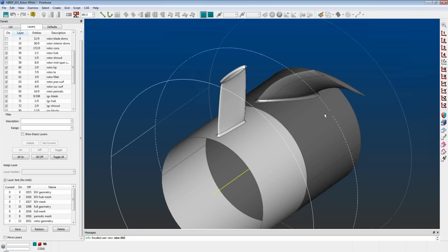It's the combination of these characteristics that makes this a challenging geometry for a structured mesh, and it's particularly true for the rotor blades. Before I show you the mesh, one constraint I imposed on myself was to keep a one-to-one point matching on the periodic boundaries, as not all CFD solvers can handle many-to-one periodic boundaries. And since I'm going to publish the grid I'm showing you today, I want it to be usable by as many CFD solvers as possible.